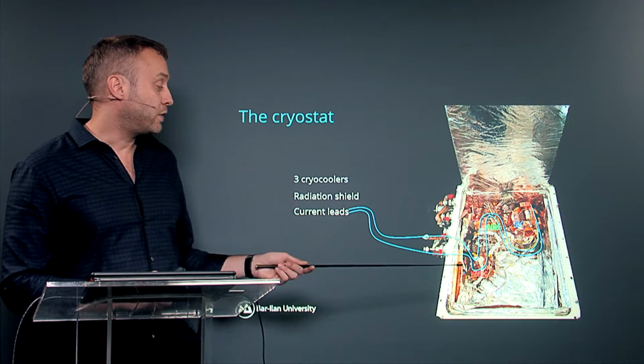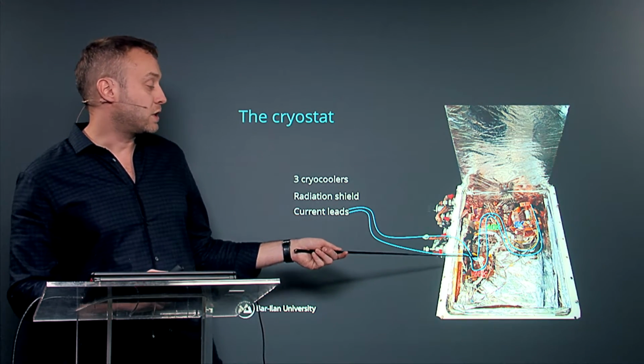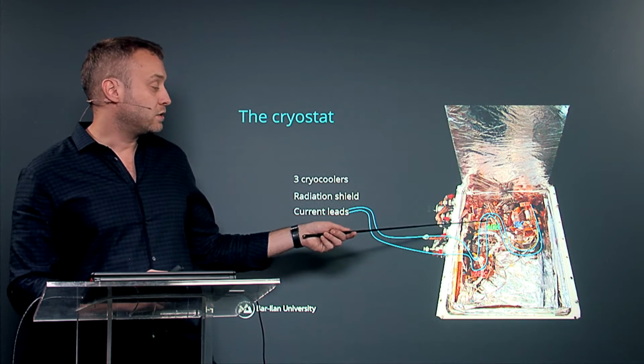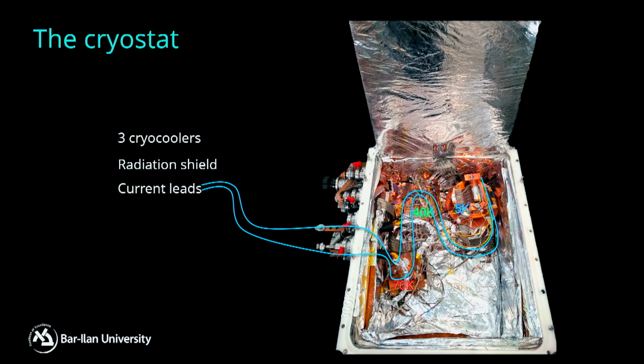The first stage is to cool it to 70K, then 40K, and just after that it goes to the superconducting specimen. This is done to absorb the heat that comes from outside on the first 2 stages and to reduce the heat transfer to the specimen itself.